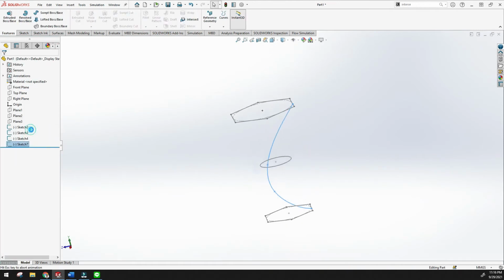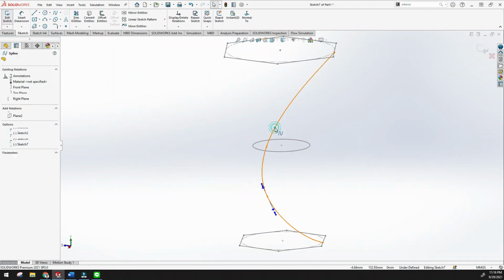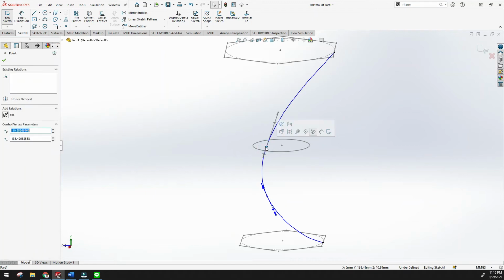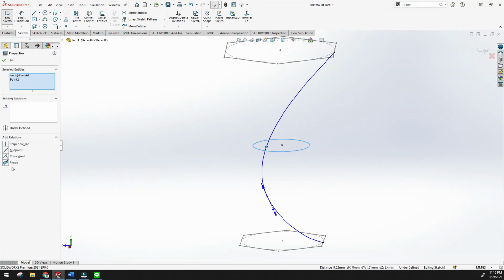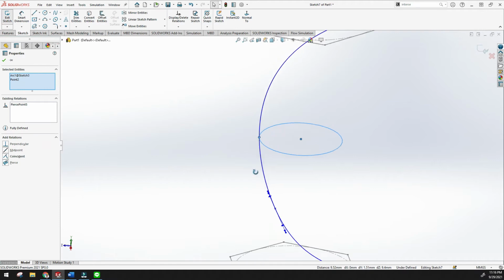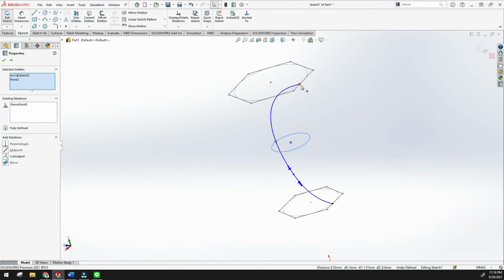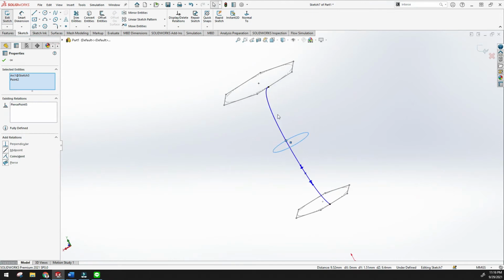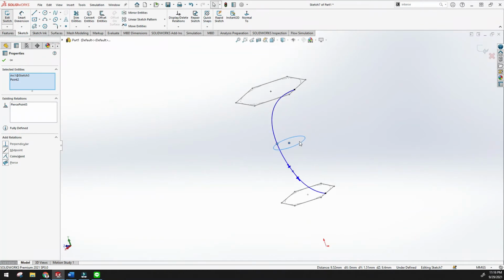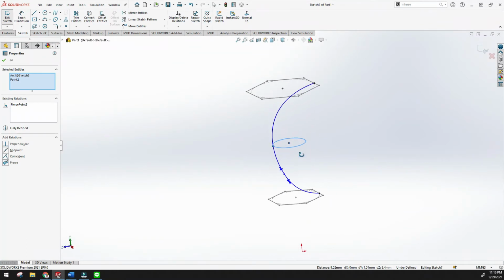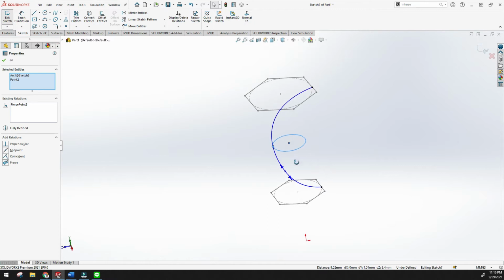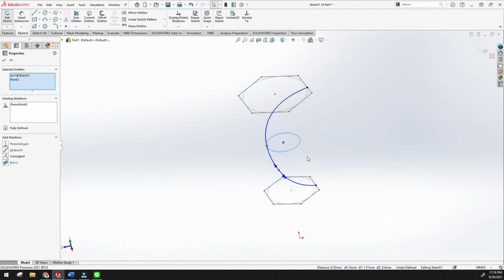And if we click this point and this circle and try to pierce, here it is the point and automatically it will pierce from here. But you will see the guide curve should be straight, like from this side. So this guide curve should be pierced this side and then this side, so it should be the same side. So how can we create them? And in this circle it's not intersections. Okay, so just go back, Control plus Z, like undo.